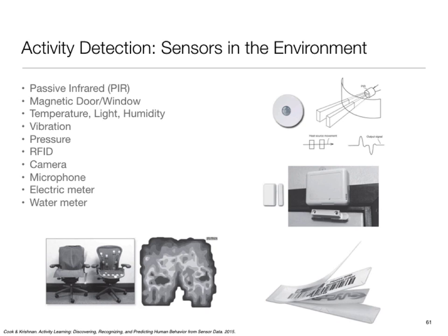Sure. So is that all done in software? You can do it either way. You can have the A to D converter do the random sampling for you. There are chips like that, as well as you can do it in the driver which is driving the A to D converter, or you can do it entirely on the digital side. That is, your A to D converter is still sampling at Nyquist rate, and you are just subsampling from that. Right. Okay, so in which case it's entirely software.